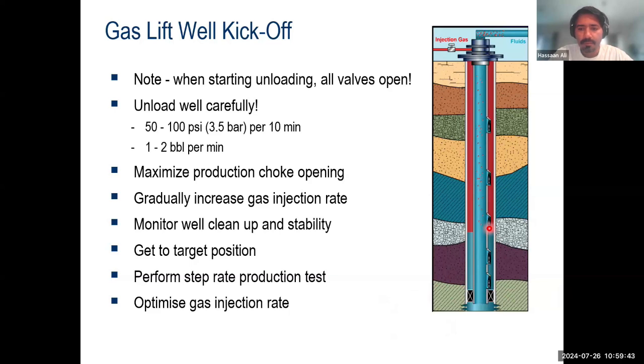Secondly, about the well integrity, or uncontrolled exposure of the well fluids into the surface. The back check in the gas lift valve that I talked about is a barrier-rated component for deep sea and offshore applications. It is tested to API and Statoil standards to ensure that it will not let a communication happen between tubing and the surface. While this is the responsibility of the gas lift valve, the rest of the prevention of exposure of the wellbore fluids to the surface is primarily your wellhead's job. The wellhead is the component that will prevent any uncontrolled exposure of the hydrocarbons.